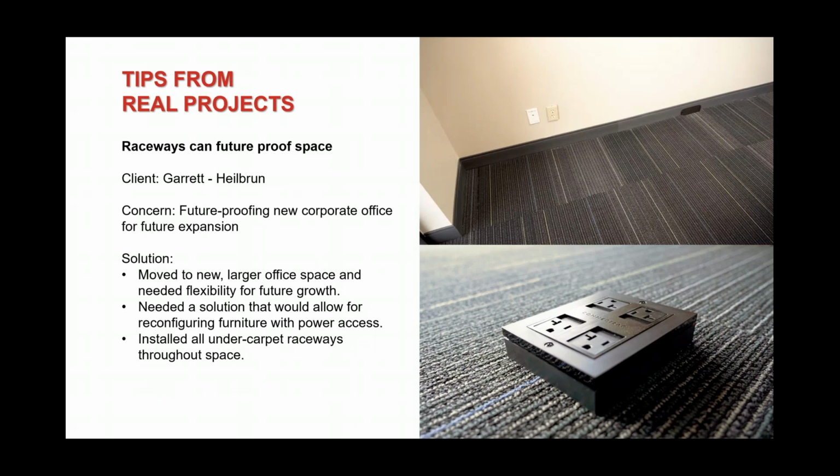Raceways, this is, I guess, my last slide. Sorry about that. Raceways also future-proof space. If you're growing and you say, well, my office is going to change here in 6 months, what do I do? Your company says, we're doing this as a temporary, what do we do? Well, you consider raceways. This is an under-carpet raceway, but it's totally removable. It gives you that freedom to change it with hardly any work.